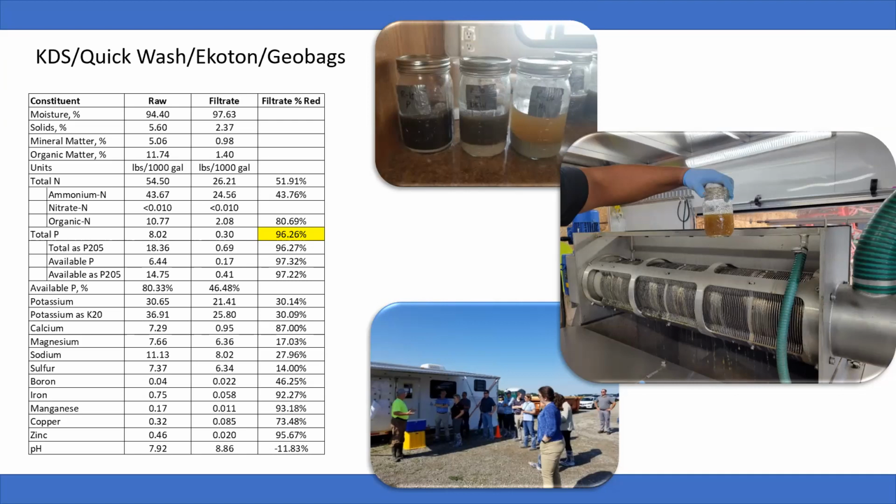We've tried several different mechanical pieces of equipment. The picture here is a multi-disc screw dehydrator. That's a series of discs with a screw in the middle of it, and basically it pushes that manure through and gives you a nice cake at the end. It does require a little bit of polymer to make sure you're being efficient with it.